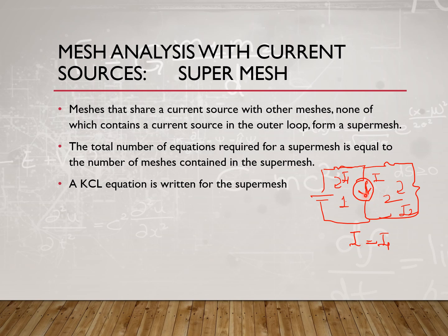And this current source I is also flowing down. So it's basically following the direction of I1. So we can write that I is equal to I1 minus I2. It's a resultant current, right? So now the first step is done, that you write the KCL equation. Now you write a KVL.